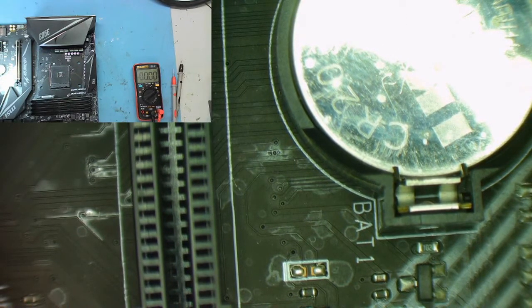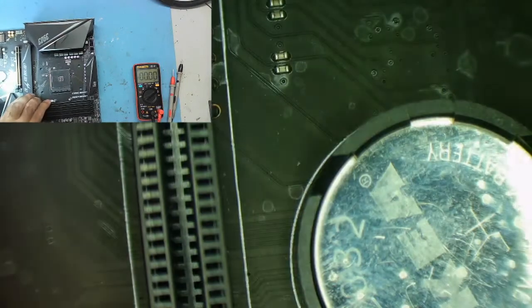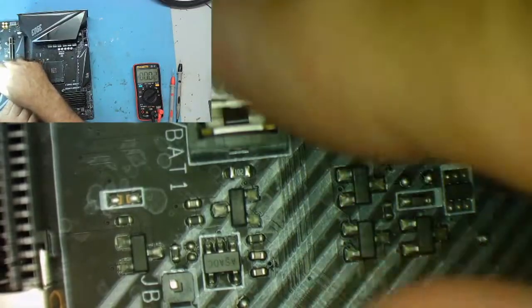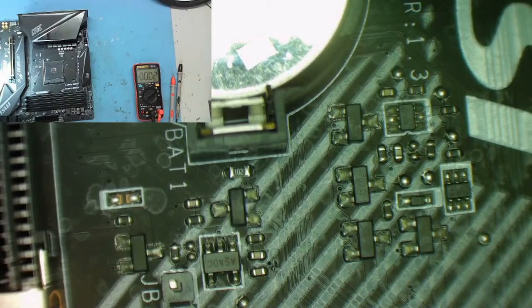I think it's going to vary a bit from board to board, but anything in the range up to about 10 microamps or so is considered normal. I've seen them where they draw like 30 milliamps, and that's a short somewhere, or effectively near to a short on the board around the real-time clock. But when you find that, the battery's going to be flat already. Okay, so that looks reasonable. So it's obviously running the real-time clock. If the real-time clock isn't running, the board will never start.